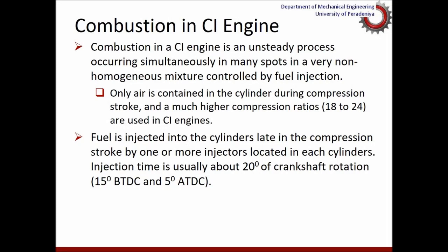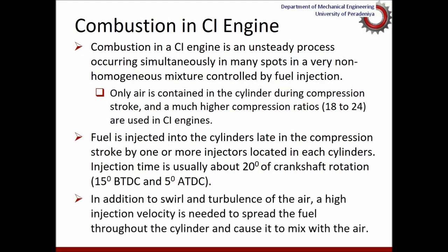Injection of fuel takes place over about 20 degrees of crank angle rotation, starting about 15 degrees before top dead center and going to about 5 degrees after top dead center. And injection pressure is usually very high.